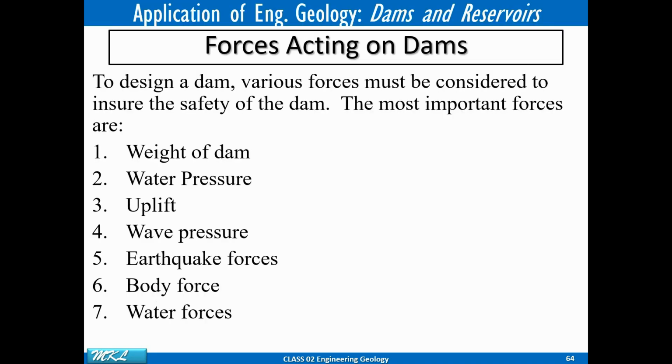so what are the forces generally acting on the dam? To design a dam, various forces act on the dam, and to ensure the safety of the dam you have to consider and tackle these forces. So the weight of the dam is there, water pressure is there, uplift is there, wave pressure is there, earthquake forces, that one is the most important one. You might have read or you will be reading earthquake resistant building design, earthquake resistant foundation design or earthquake resistant dam design in your civil engineering course. There you will see that you have to consider earthquake very seriously.